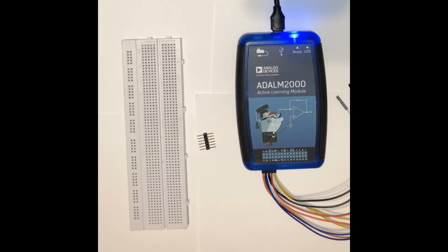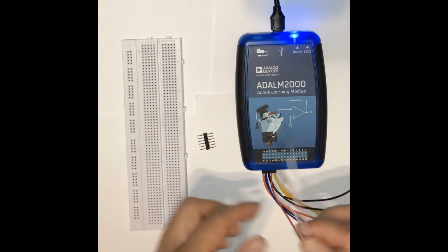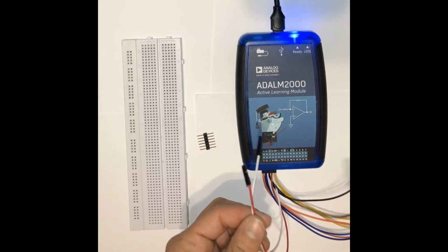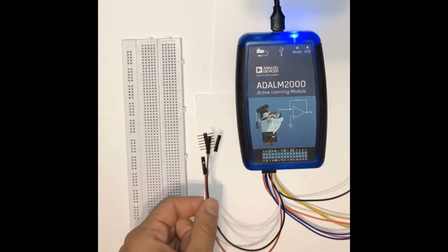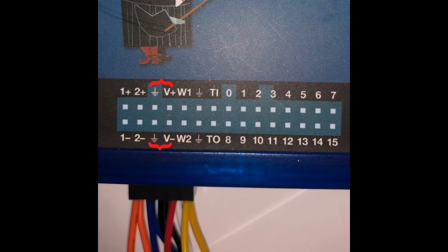As mentioned in the previous video, a power supply is simply a tool that allows one to supply power to a circuit or component. The M2K can provide any amount of voltage ranging from -5 to 5 volts. To demonstrate the power supply, we will use a breadboard, a header, and the red and white leads from the M2K and one of the black ground wires. These wires correspond to the V+ and V- pins and the ground symbol pins from the pin diagram of the M2K.